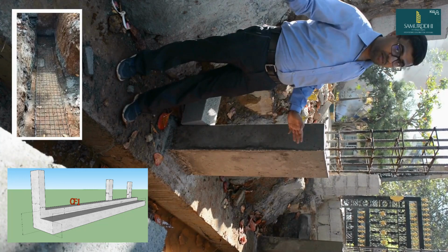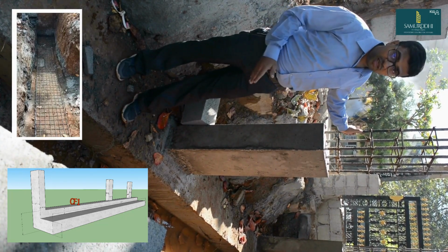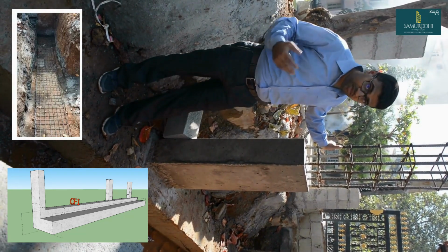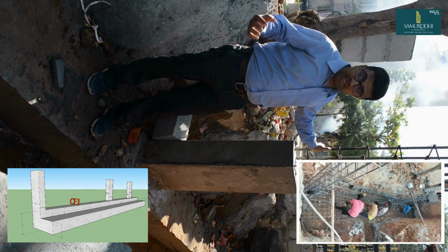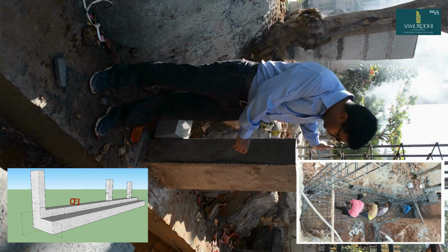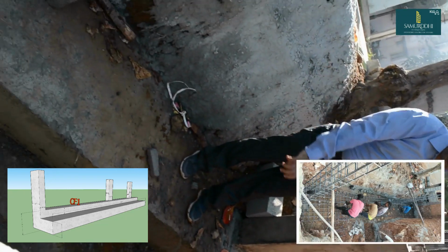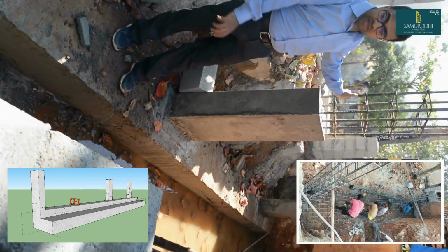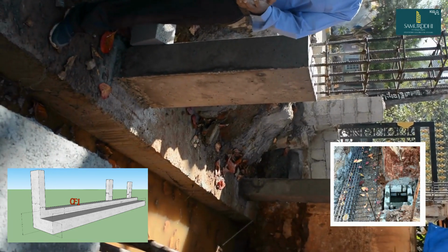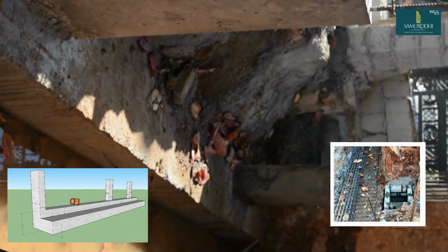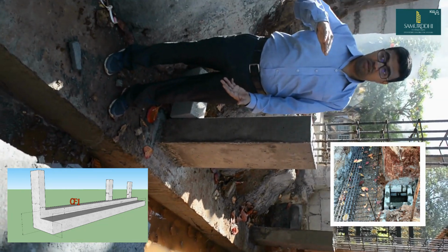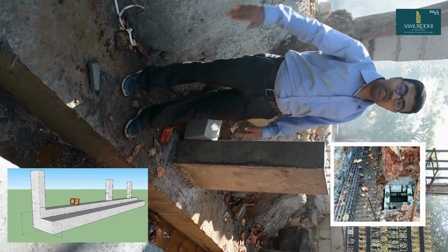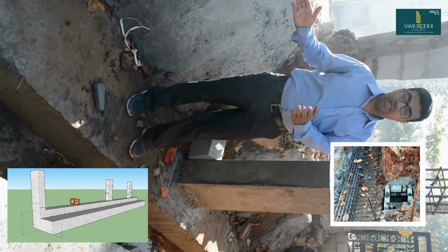No. Over it there is a beam of 18 inches by 18 inches depth, which is connecting all the 3 columns in one stretch in order to withstand the load and transfer it uniformly to the entire length or width of the site, to be more effective in transferring the load from the columns to the foundation. So all the columns in this stretch are designed at the site edge.